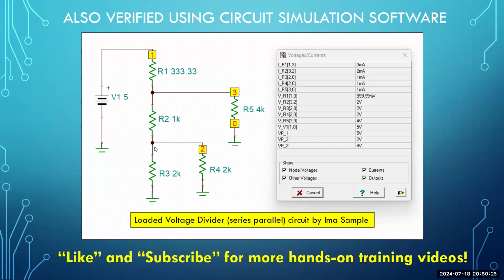I can't change these to alpha characters in the simulator, but we know that this top of R4 is point C in our schematic. So this was required to be 2 volts. And what do we have at point C, which is voltage 0.2? Right here, voltage of VP2 is 2 volts. So the currents jive and the point voltages jive.